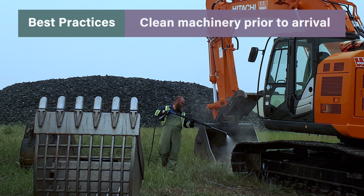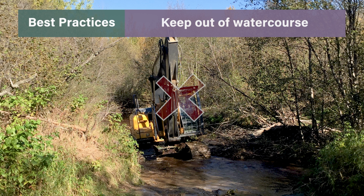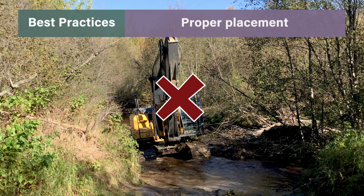Machinery should be cleaned prior to arriving on site to prevent pollution, the spread of invasive plants, and the spread of aquatic invasive species. Keep machinery out of the watercourse channel and away from riparian areas. Avoid fording. These practices can cause damage to the aquatic ecosystem.